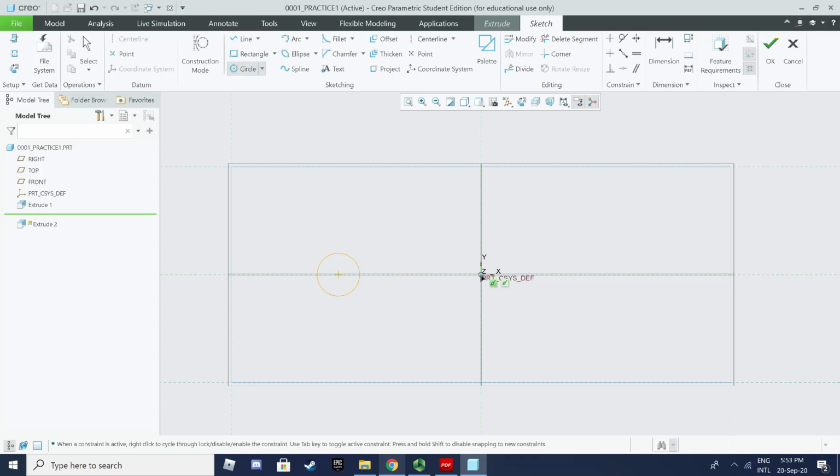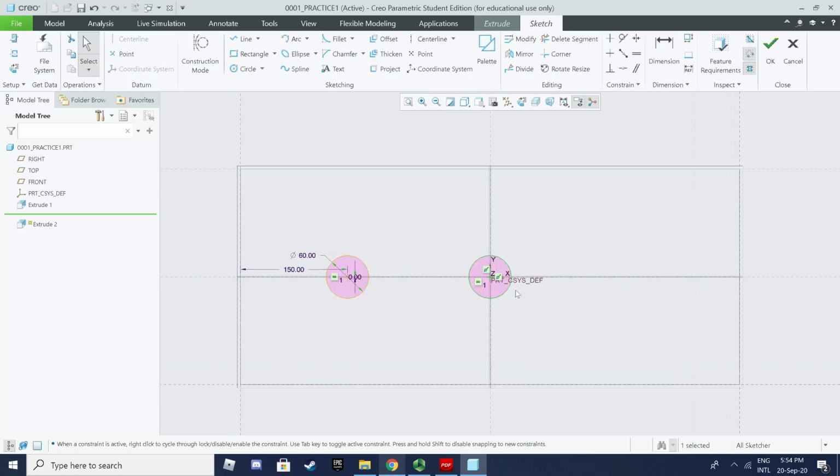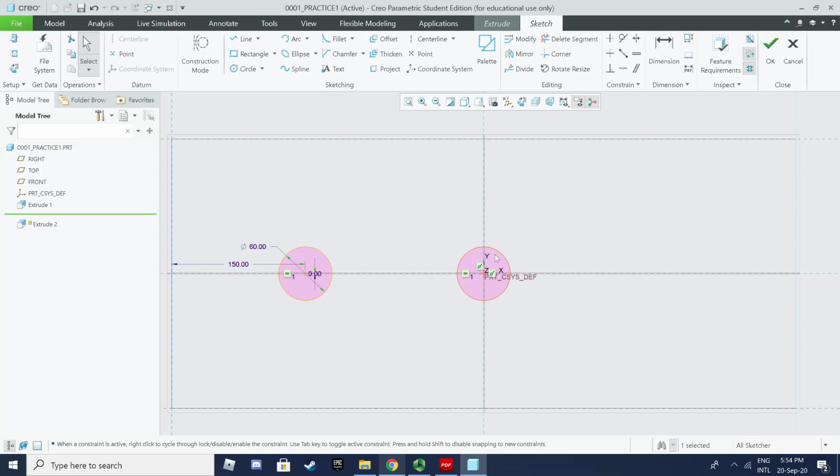Okay. Let's say I want to make this second hole, maybe exactly at the center of the rectangle. Then you can see I start to make the second hole, and you can enlarge it or make the hole smaller. But if you just play around and try enlarging it, suddenly it stops here. You can see the equal sign there, which means the second hole has the same diameter as the first hole. Exactly here, no need to mention another.